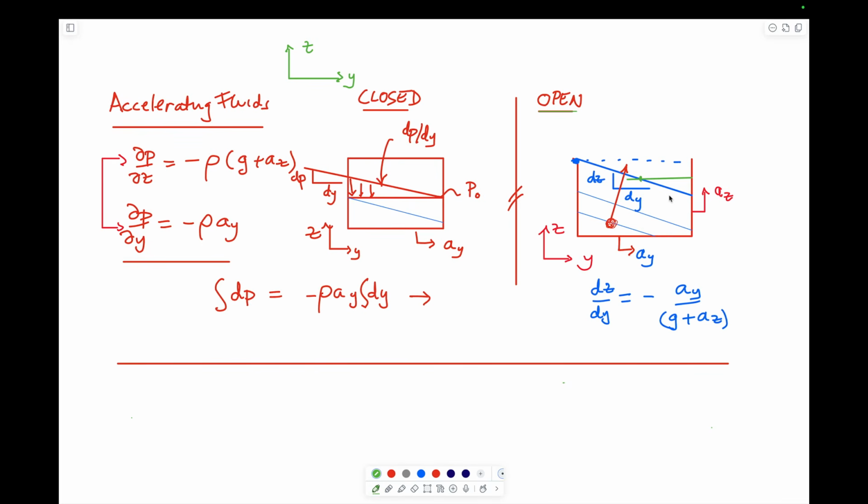So that when it accelerates, the back elevation comes up, the forward elevation comes down. And we use this by defining a line which has 0 pressure on it and no change of pressure as you go along it. The standard solution for that is that the change in elevation of the free surface with length along this tank is given by this standard result.